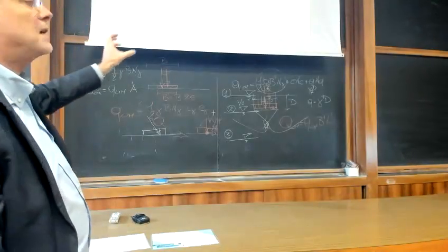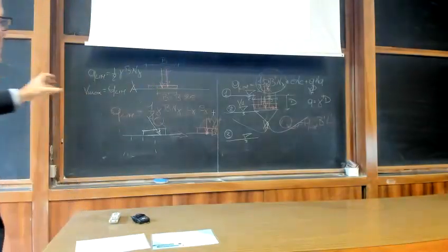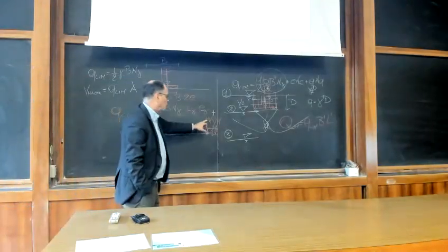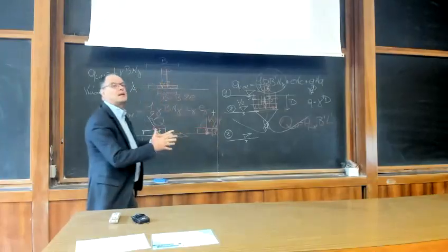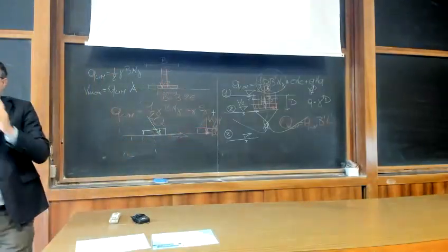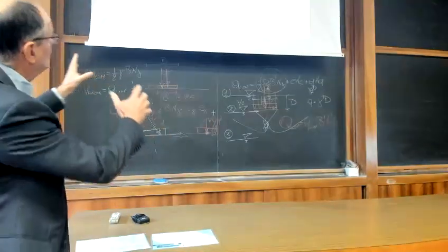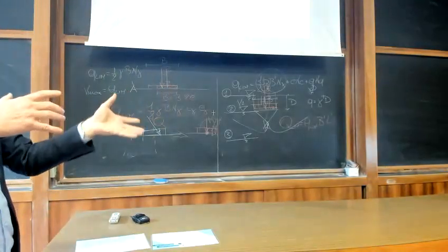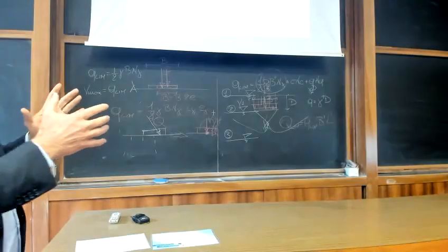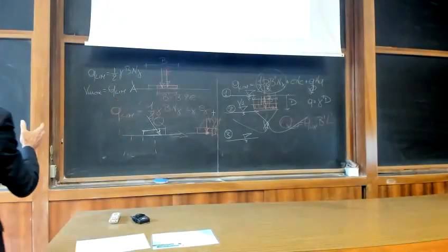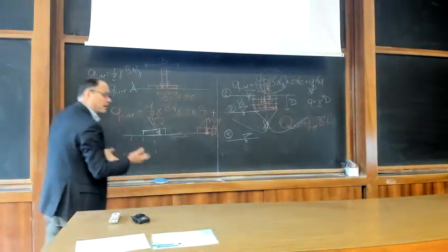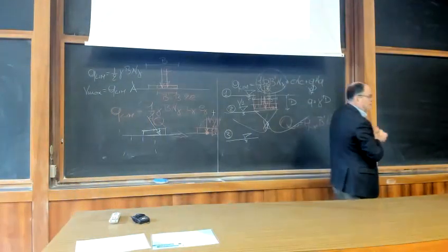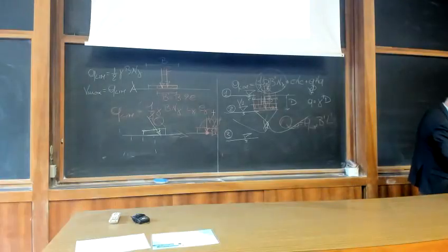And you can increase your load, taking into account the uncertainty that you have on V and H, so you can amplify the load. On this plane, you can play games amplifying the vertical component and the horizontal component in a different way. So this approach allows you to make use of partial safety factors as required by the Eurocodes.